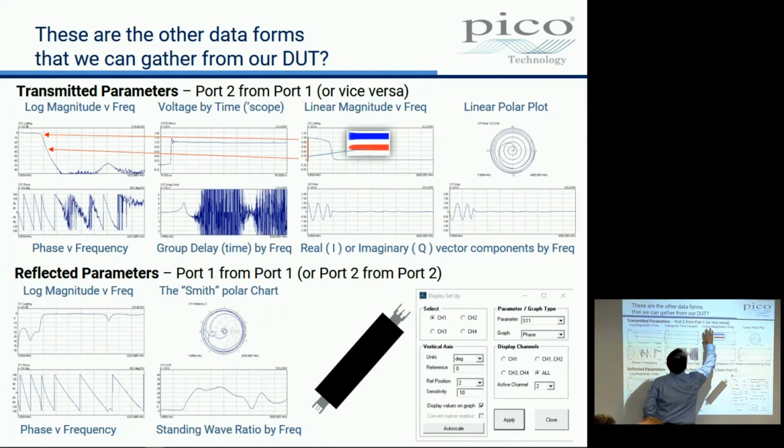Let's instead change this scale to log, in which case that whole bit there, you'll agree on a scope you can see 1 down to 1%, say. And if you map 1 down to 1%, across here it maps to 0 to minus 40 dB. So this part of the curve is that. That doesn't show you this. So this is log magnitude by frequency. All I do is go boom, log magnitude, and I get that plot there. So that plot and that plot are directly related to one another.